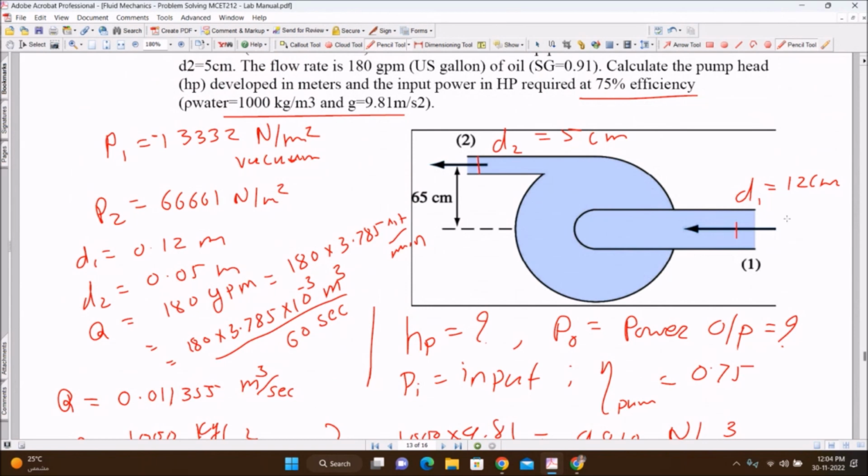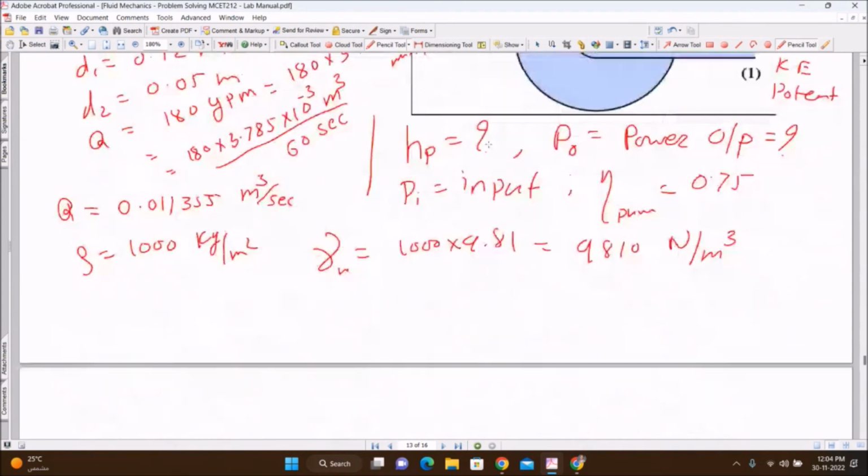The energy available at inlet is a pressure energy, kinetic energy, then a potential energy due to the height, and some energy from the outside source or from the machine. Okay, so this is the energy at inlet is equal to energy at outlet. Some energy is added in the water by the pump and same energy at outlet, potential energy, kinetic energy.